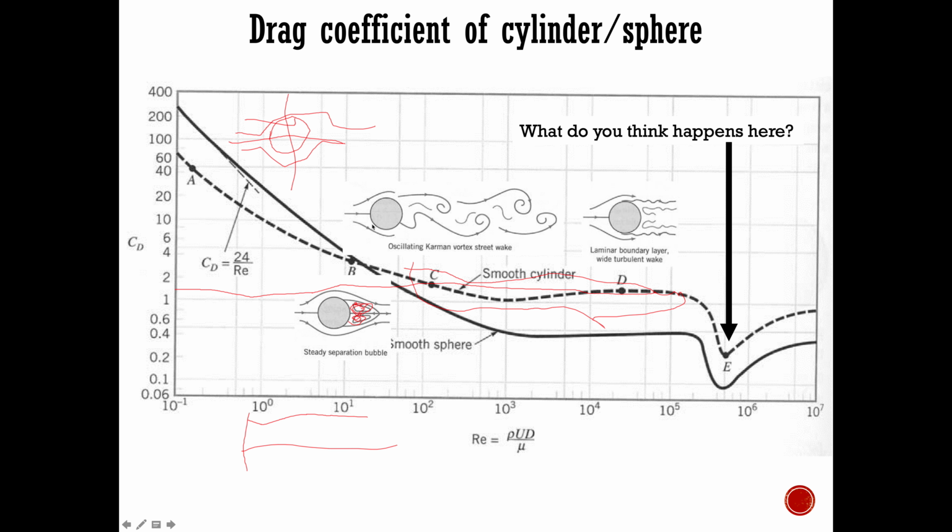And as you keep increasing the Reynolds number, at some point the von Karman vortex street is going to stop, and you have just pure flow separation. This separation happens right around the top and bottom portion. So you'll get a fairly thicker wake, which also increases the drag coefficient just a little bit, as you can see. Then it dips down and then rises up again.